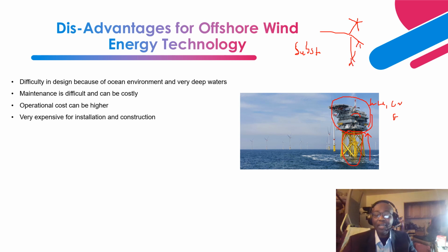You can have different arrangements. Sometimes you can have a redundancy in the arrangement. It's all based on cost, right? The more redundancy you have, the higher your cost. To achieve that closed loop, you can have other loops, and that basically allows you to best deliver electric power to your connection point if you should have a fault in one of the feeders.